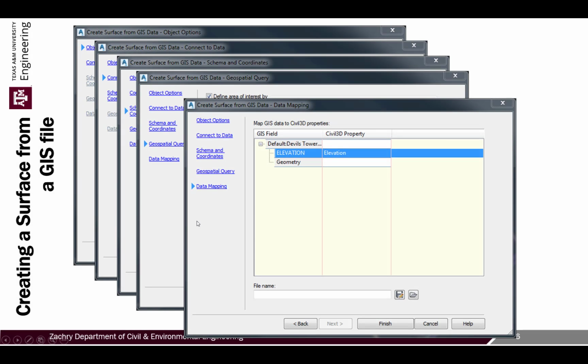So what I want to do now is create a surface based on that GIS file. I would go back and find the zones that I want, pull in that data, and then extract it, because it comes in as a zip file. Then I'd be ready to go. So I come in, grab it, extract it, and then I need to create a surface.